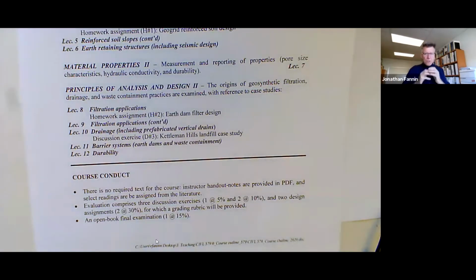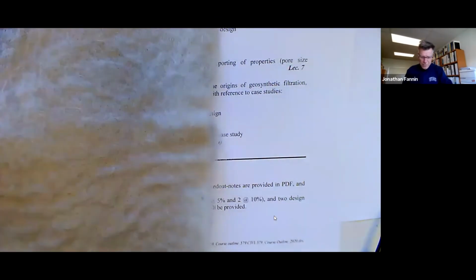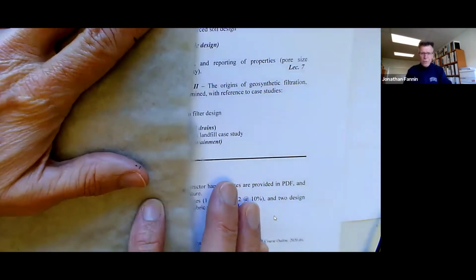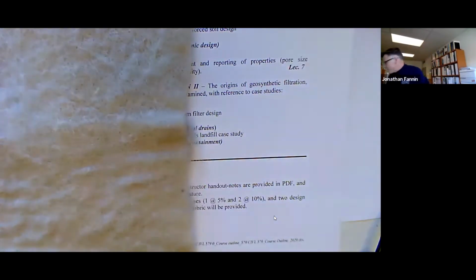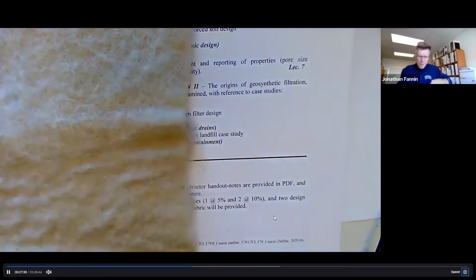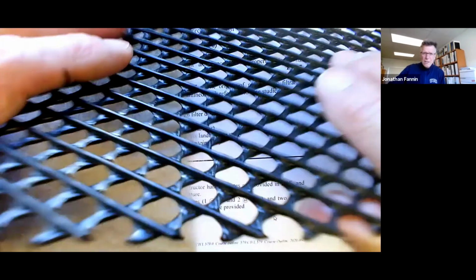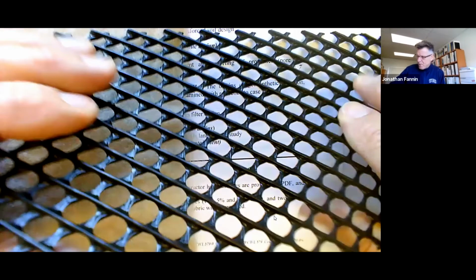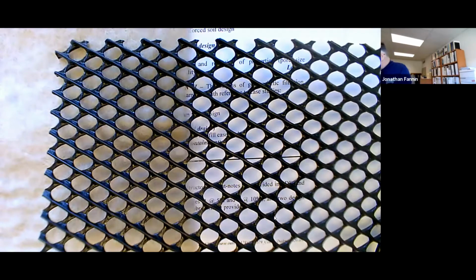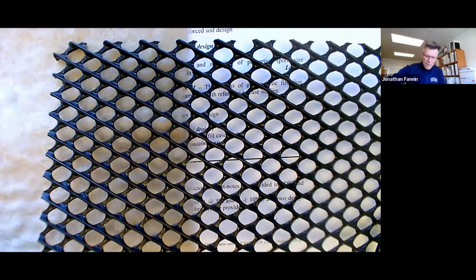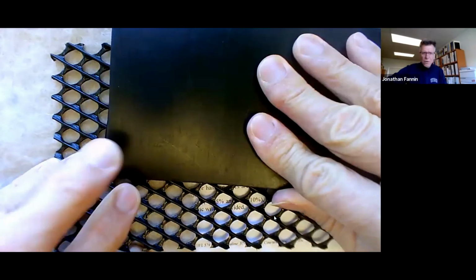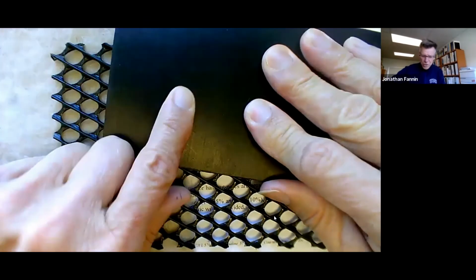And in switching to this topic, and an interest now, we're almost stepping away from geogrids if they're primarily used as the material of choice in reinforcement of walls and slopes. And we're moving to a world of geotextile filters, on occasion geonets as a preferential drainage medium, or on occasion the very low cross-plane conductivity of a geomembrane.